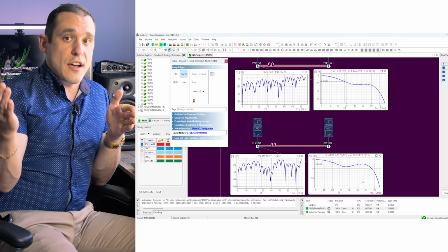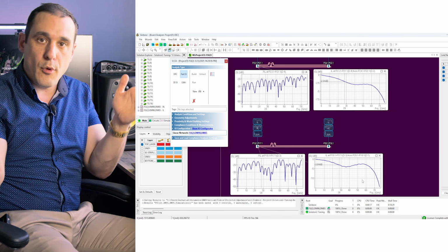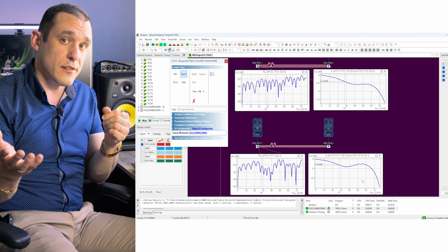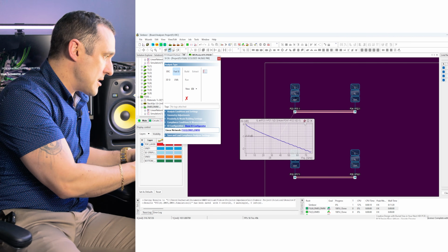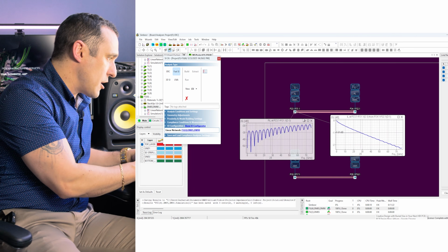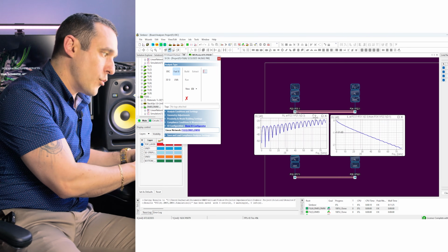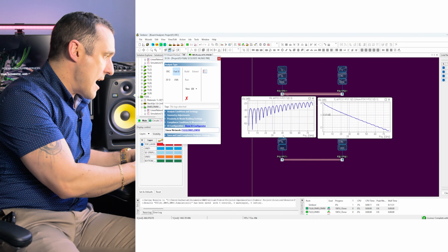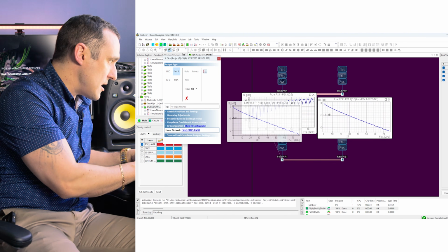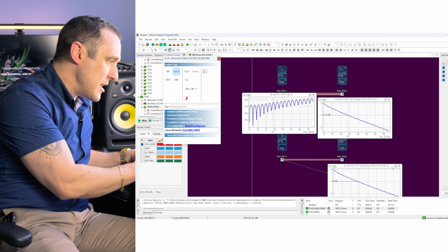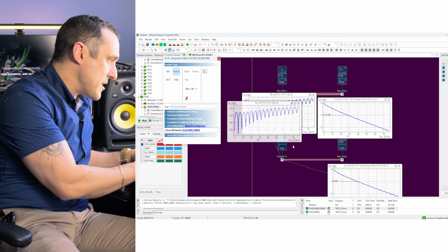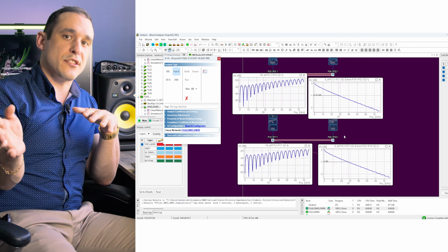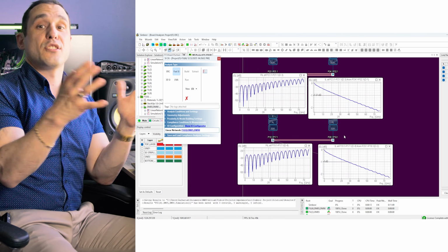So that's partially because of the greater mode conversion, but it's also due to the fact that when we put the traces closer together, they have to be narrower, so we get a little bit more copper loss as well. Just for comparison, if we bring up the insertion loss in these curves here, you can see here that we already have -1 dB of insertion loss at 28 gigahertz in the widely spaced traces. And if I bring up the other ones, you can see here, we have also about -1 dB at the same frequency in the traces that are spaced closer together. So we still get some pretty good results here that illustrate what happens when you add in that length tuning section. It does add into the insertion loss as well as the return loss.